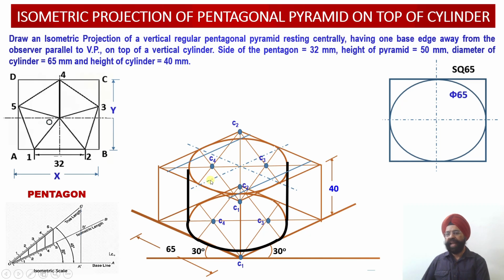So these two projector lines in this direction will be drawn such that this distance, please check, O to this one, will be plotted on this side. Similarly, O to 4 distance will be plotted on this side. Now please check. This is the location of my Y over here. So this is my distance of X. This is my distance of Y. And this distance of Y has been obtained such that, again I am repeating, this distance is equal to axis to this base distance.